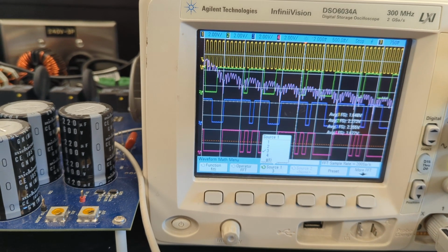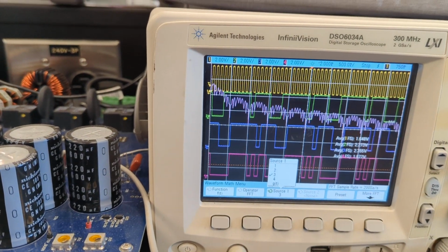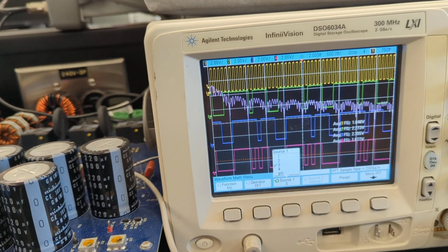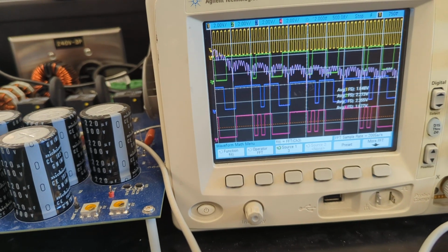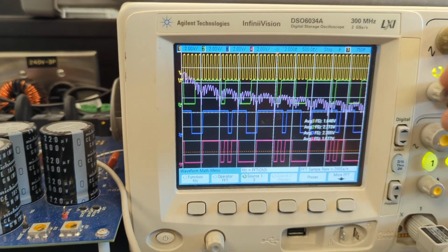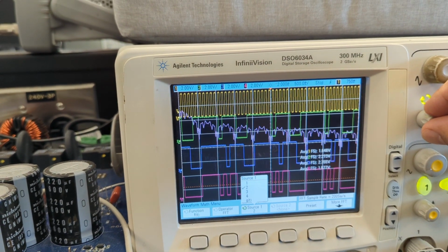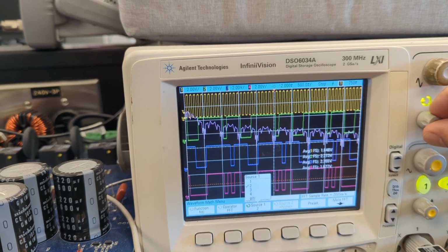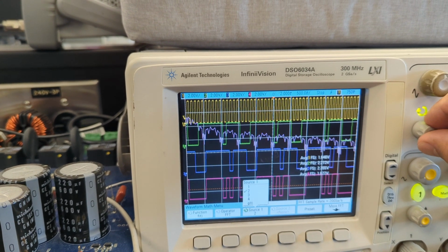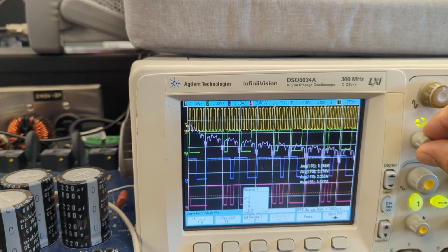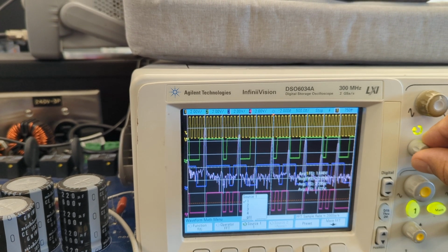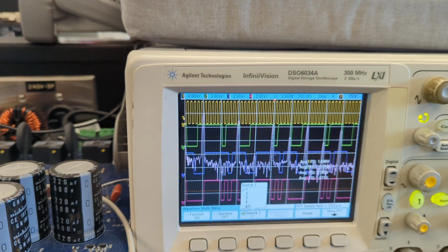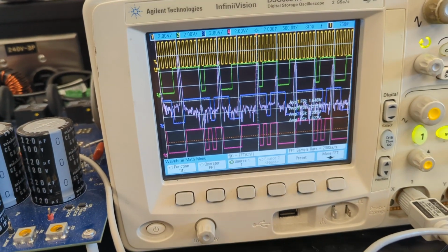Now really you have to look at the A0 constant of the FFT, the DC average, to get it to work. But you can see that using this as a kind of pseudo-random PWM, you're spreading the energy of those harmonics, which are hard to filter out, making it broad.